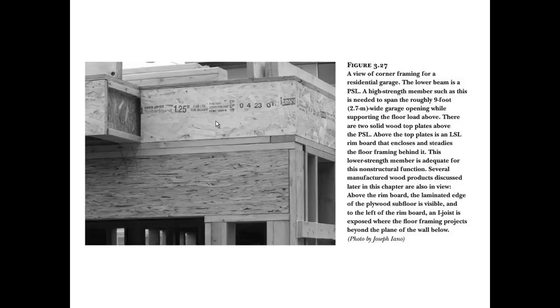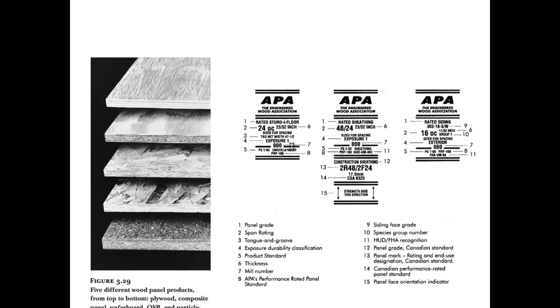It has fiberglass or reinforcing within the glue sections to give it strength. That's used in very long spans in residential construction where we need a lot of support. Garages underneath, for instance, we see a lot of this, and up above we see this LVL type construction.